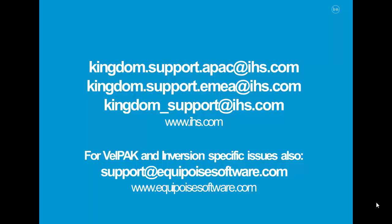A question here on what other volumetrics can be calculated. Well, at the moment VelPAK only computes gross rock volume. If you want to factor in net to gross ratio, porosity and all the other factors, you can do so, but this will be done in the Kingdom Volumetrics and Reserve Estimation tools. There's two places in Kingdom and Kingdom Advanced you can generate these volumetrics. All you need to do is export the appropriate grids from the VelPAK model back to the Kingdom project tree and then use those functions.